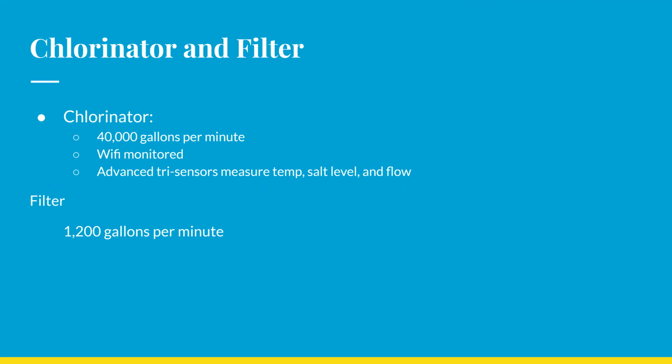So to deal with the cleanliness of the pool and water slide, we decided to add a chlorinator. We chose to add the Autopilot ChlorSync Salt Cell CS50 chlorine generator. The CS50 has the capacity to chlorinate a 40,000 gallon pool, and our pool size was calculated out to hold approximately 37,000 gallons of water. This chlorinator should also be able to chlorinate the water in the pipes as well.